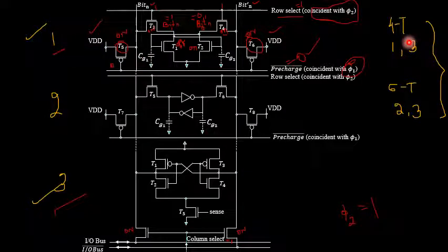So when you are using such cells in the random access memory arrays, the area of each cell should be kept minimum and the transistor should be of a minimum possible size. In case of a VLSI design system, we are mainly concentrating upon the low area. So in order to have the least area, you are going to choose the size of each and every individual transistor to be as minimum as possible. This makes them incapable of sinking large charges very quickly.